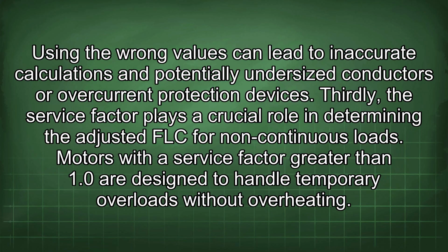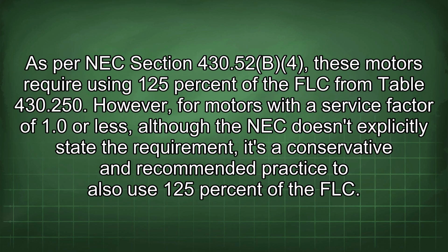Thirdly, the service factor plays a crucial role in determining the adjusted FLC for non-continuous loads. Motors with a service factor greater than 1.0 are designed to handle temporary overloads without overheating. As per NEC section 430.52(B)(4), these motors require using 125% of the FLC from Table 430.250. However, for motors with a service factor of 1.0 or less, although the NEC doesn't explicitly state the requirement, it's a conservative and recommended practice to also use 125% of the FLC.